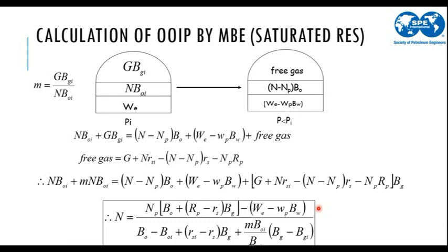And that's why I talked about the combination reservoir specifically. Because imagine that we have a depletion reservoir. We said the depletion reservoir is a reservoir that has free gas but not a gas cap and not a water drive. So if we want to calculate the depletion reservoirs using this general equation, the first thing we would cancel is this term. All of this term would be cancelled.